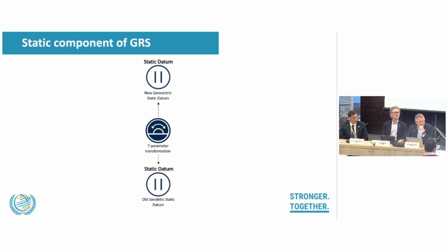So all the surveying equipment producers supply the transformation in the equipment already. So the surveyors have been using this for 25 years now. The GIS community only followed a few years ago, so we now have the official transformation in the EPSG database and also in ArcGIS and QGIS.